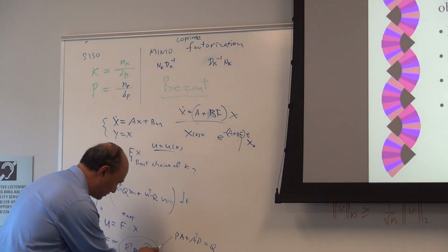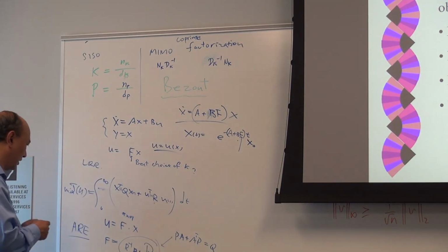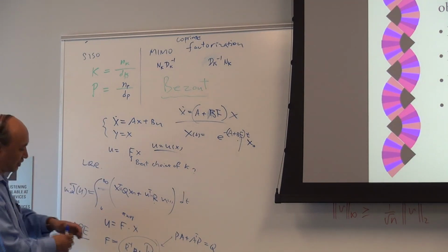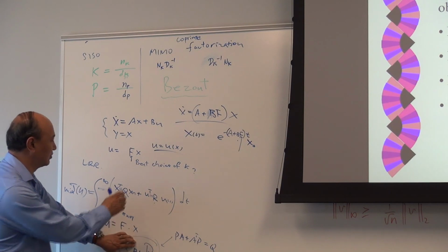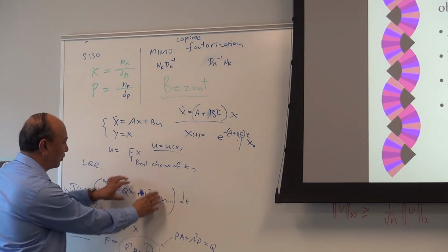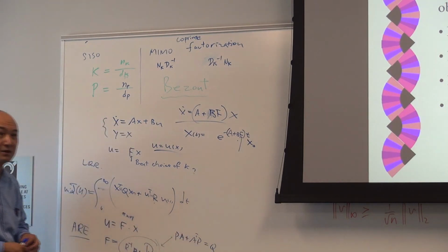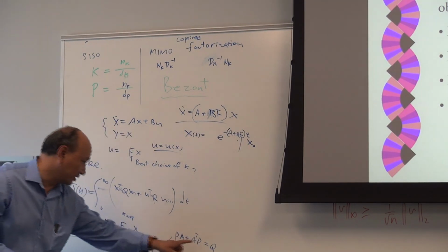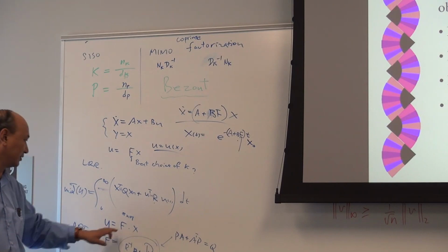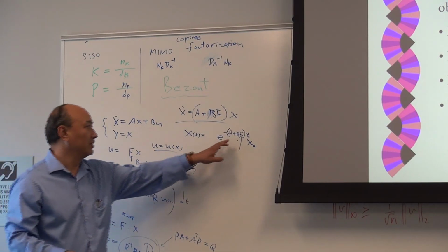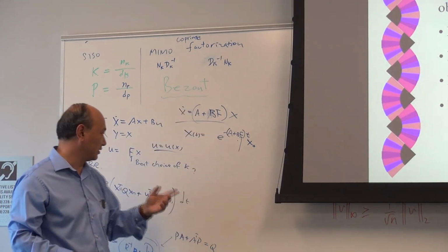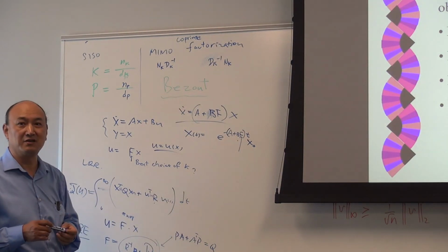So you get this. So you can see the design tuning knobs are here, because you choose different Q and different R, which are weighting matrices, and they will show up in here. So then you get different P, so you get a different F, and you decay differently. So that's the solution.